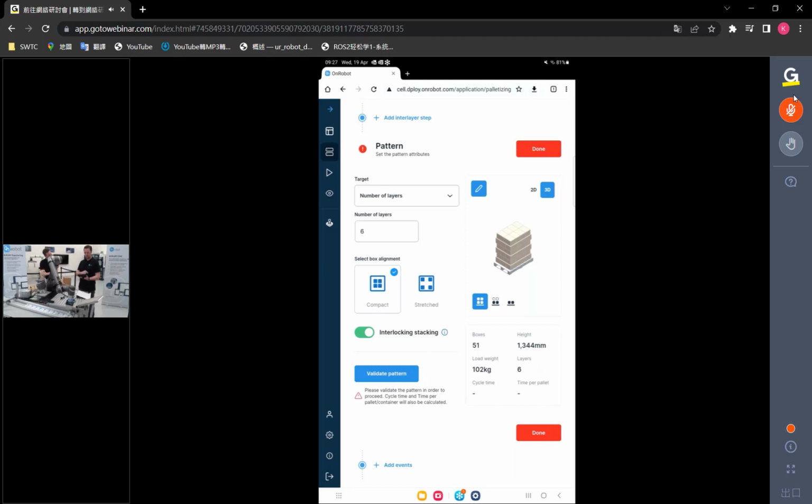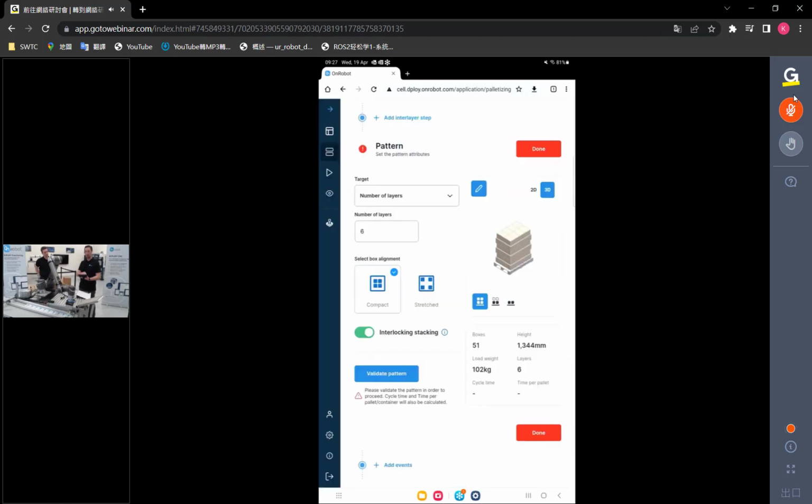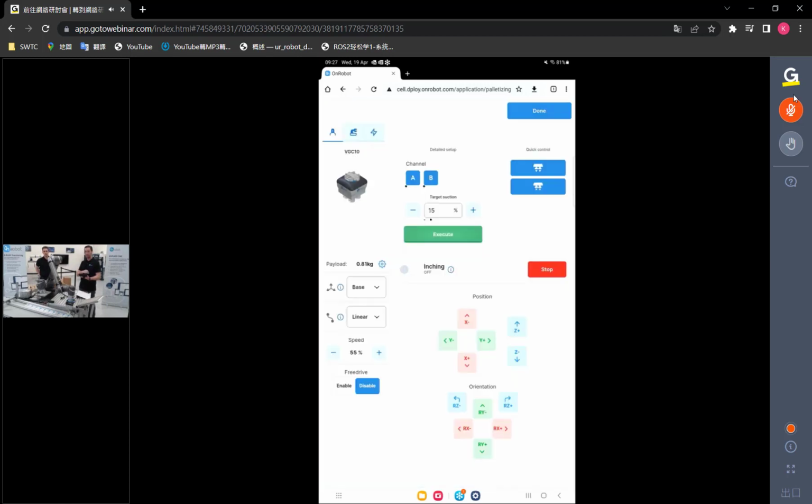Yes, we have not done that too much today. When we are going to move a robot around, we have this jog screen. That would be the small joystick button in the side panel. If we press that one, we get to this jog screen, and right now we're jogging in base, where we can move the robot around, or we can switch it to tool coordinates, and then we need to know how the tool is actually oriented. So if I move it in tool, then that will be what is operated here.